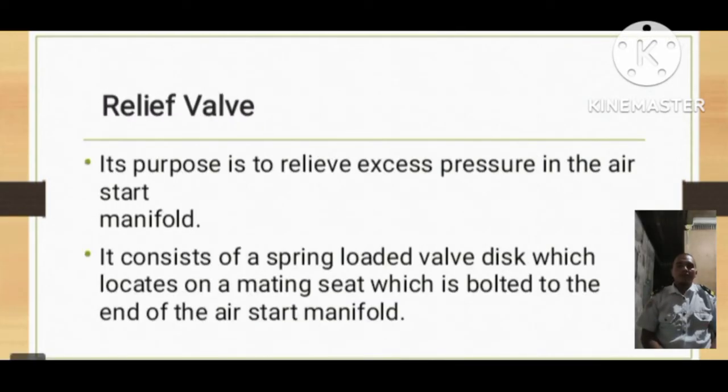So the relief valve's purpose is to relieve excess pressure in the air start manifold. It consists of a spring-loaded valve disc which locates on a mating seat which is bolted to the end of the air start manifold. When the force exerted on the disc due to excessive pressure is greater than the spring force holding the valve closed, the valve will open and release the excessive pressure.